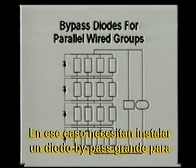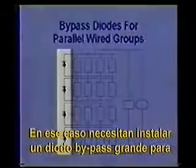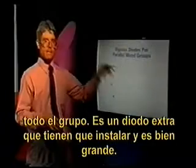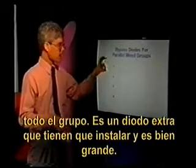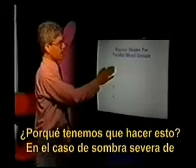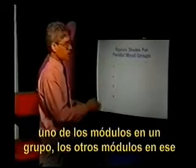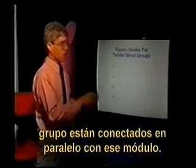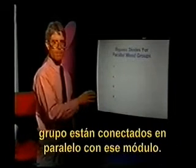In that case, you need to install a large bypass diode for the entire group. It's an extra diode that you have to install, and it's a very large one. Why do we have to do this? In the case of severe shading of one of the modules in a group, the other modules in that group are wired in parallel to that module.